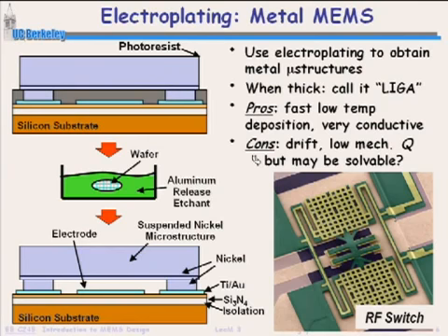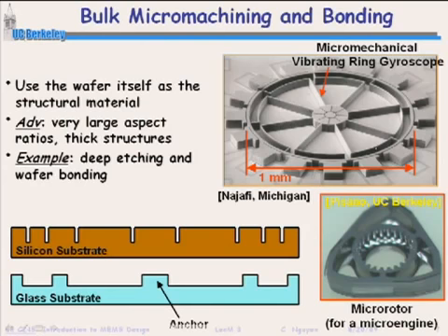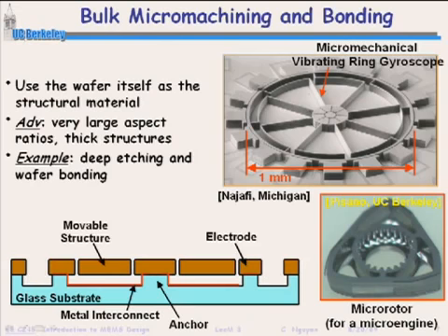I also talked about bulk micromachining. So here's a process that you saw already. So you etch into the silicon, take a glass substrate, etch anchors into this, flip the silicon over, bond it. So here's a bonding technology that was sort of pioneered in the MEMS area. And then dissolve away that substrate to, again, end up with a freestanding device here. So lots of different ways to fab things. But all these different ways to fab things are just based on several modules that we could talk about. Film deposition, etching, lithography. So let's now talk about one of these, which is oxidation.